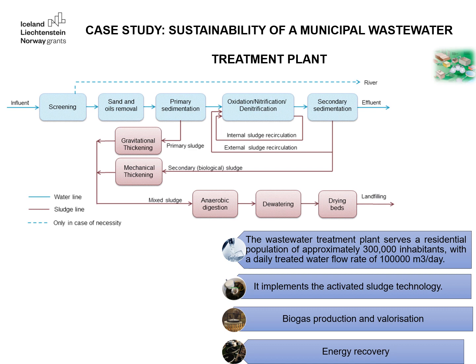Primary sedimentation. In this step, heavier particles settle at the bottom of the basin, leading to the separation and removal of larger solid impurities. Activated sludge technologies. Activated sludge is a biological process in which bacteria are used to break down organic substances in the wastewater. Nitrification, denitrification. This is a crucial process that involves converting ammonia compounds into nitrate, followed by denitrification, which reduces nitrate to gaseous nitrogen. This process helps reduce nitrogen concentration in the wastewater.